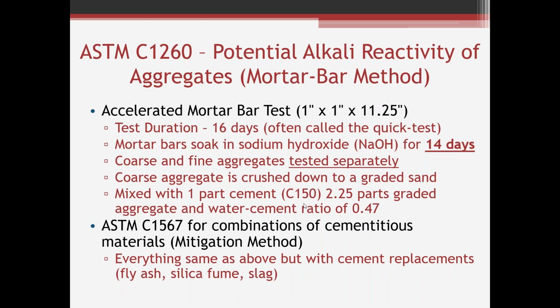So ASTM C1260 is probably the most common ASR test. Some people call it the quick test. Some people call it the mortar bar test. It's got a bunch of different names, but the test itself is 16 days. We're soaking the sample, that 1 inch mortar bar, in sodium hydroxide for 14 days.